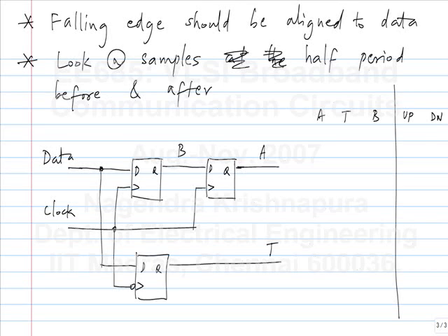Let's say we again go to a charge pump with up-down inputs. So we either raise the up or raise the down, or have both of them at 0 if we don't want any movement in the phase of the VCO. So we have 3 inputs: the transition sample, A and B. We have to find out how to relate the up and down to these things.